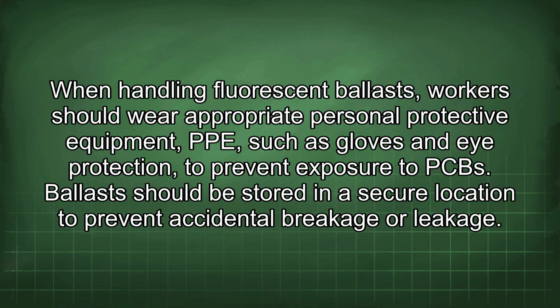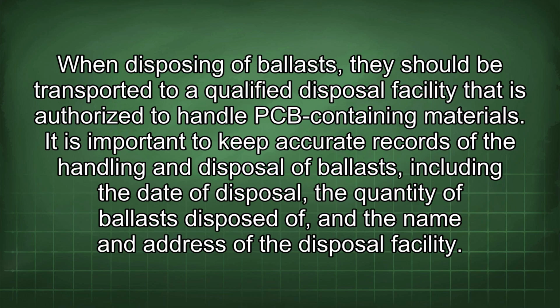When handling fluorescent ballasts, workers should wear appropriate personal protective equipment (PPE), such as gloves and eye protection, to prevent exposure to PCB. Ballast should be stored in a secure location to prevent accidental breakage or leakage. When disposing of ballasts, they should be transported to a qualified disposal facility that is authorized to handle PCB-containing materials.